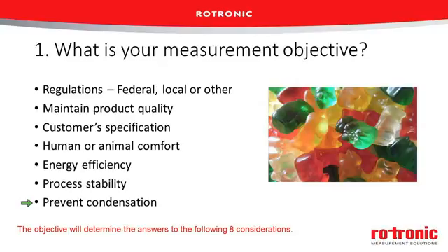One application that I saw several years ago was for the Navy. They needed to coat some tanks inside some of their ships. For them, it was very important to make sure that there was no chance of condensation forming on those walls when they're doing the painting, because the point of the painting is to prevent rust. So if there's condensation on the wall and they paint over that, A, the paint won't stick very well, and B, they'll get rust anyways, because that will start from behind the paint.